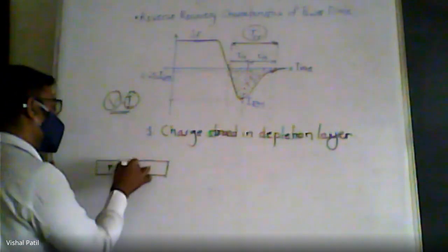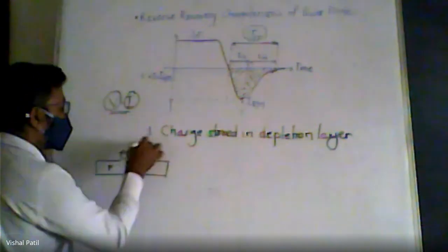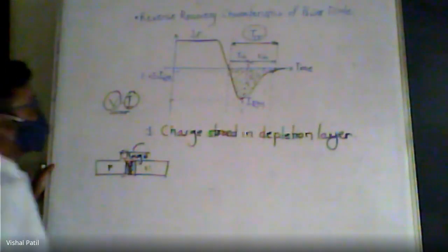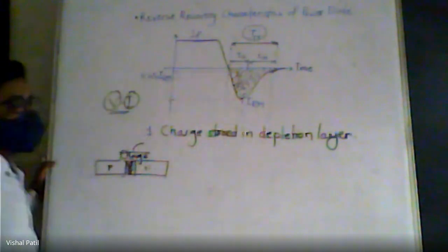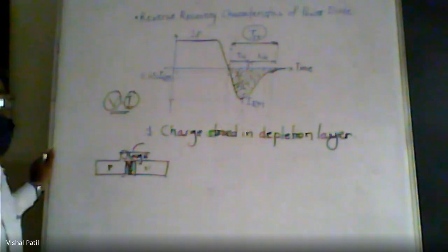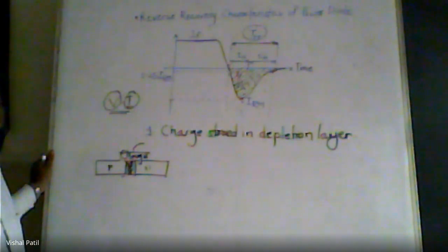Okay, so in this part we have charge. That charge is recovered in the first step. This part indicates the charge recovered by recombination of the opposite charges. Now, how is charge recovered actually? What is the physics behind recovering the charge? Because we know that in semiconducting material, in p-type there are holes and in n-type there are electrons, and naturally or spontaneously they combine with each other. That is the process. When they combine with each other, the charge is recovered. That is the concept.